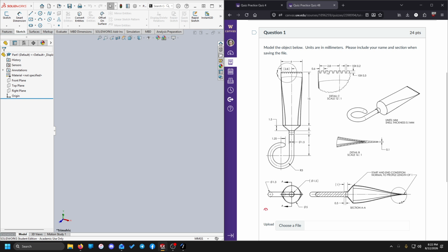And then we also see that we've got these sort of crimps on the back. We've got this sort of toothpaste spiral coming out on the front. We've got the main tube of the toothpaste. That one is hollow, so that's going to need to happen before our shell feature. We've also got the front bit here. That's going to need to happen before our shell feature. See the hidden lines on the inside there. Whereas the toothpaste and the sort of crown on the end, those are solid. So those are going to need to happen after the shell feature.